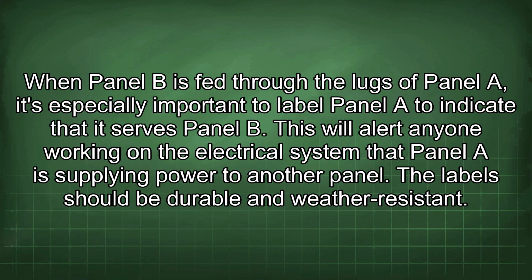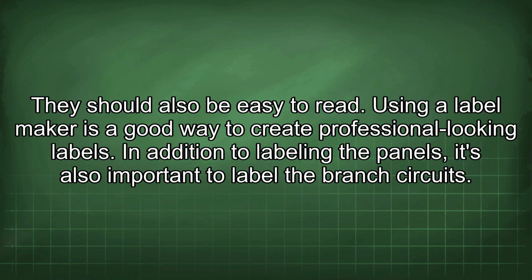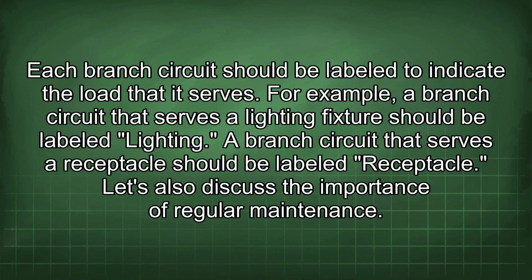The labels should be durable and weather resistant. They should also be easy to read. Using a label maker is a good way to create professional looking labels. In addition to labeling the panels, it's also important to label the branch circuits. Each branch circuit should be labeled to indicate the load that it serves. For example, a branch circuit that serves a lighting fixture should be labeled lighting. A branch circuit that serves a receptacle should be labeled receptacle.